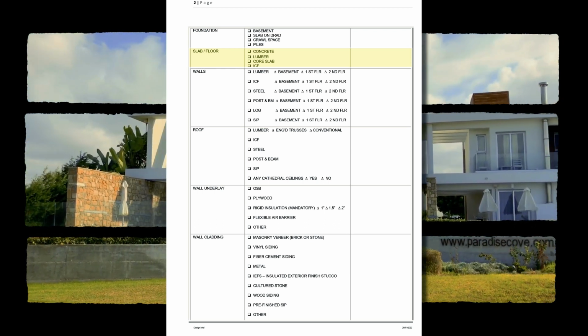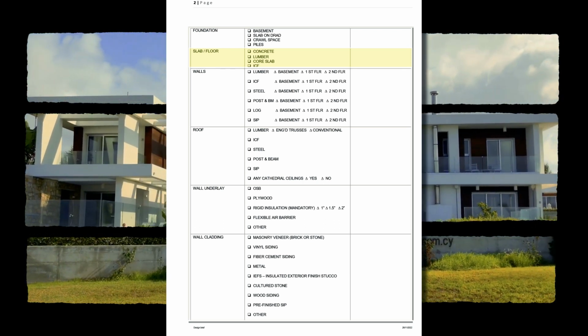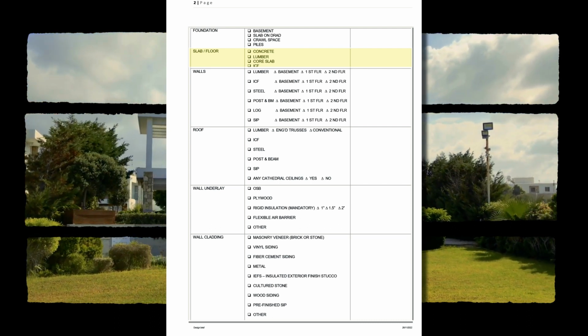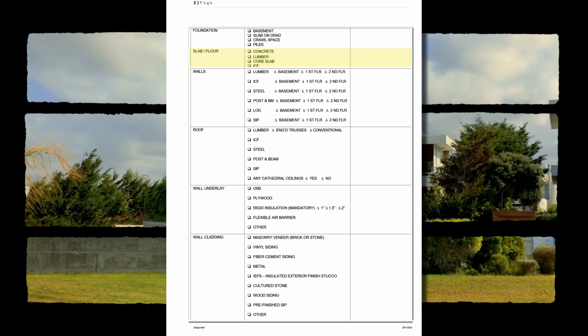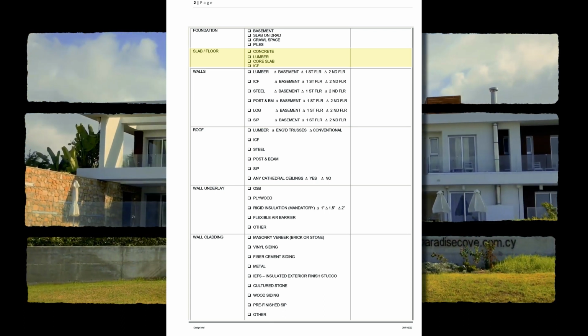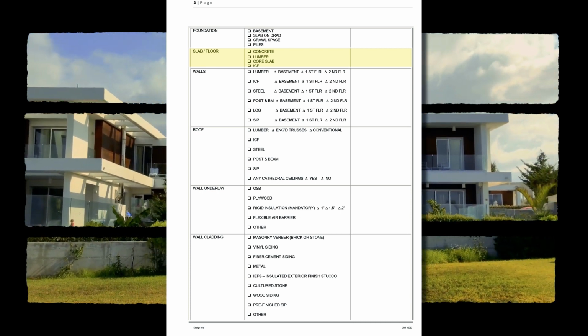Normally, below or at grade floors are constructed of concrete, and above grade floors of wood frame, made up of floor joists and a subfloor sheet type material. Other options for floors include core slab and ICF concrete floors.